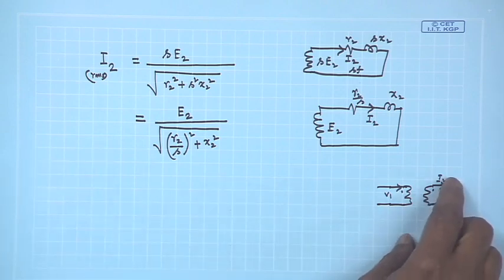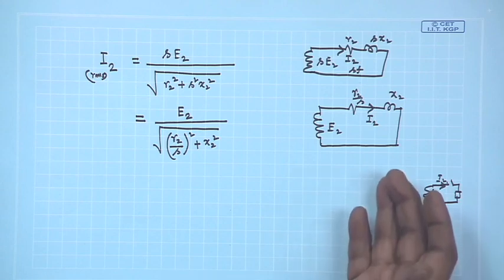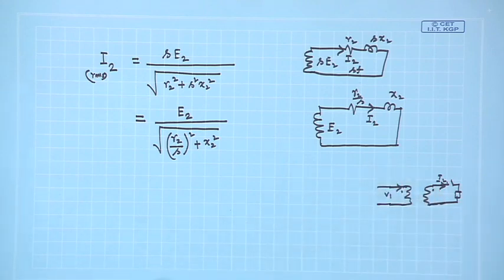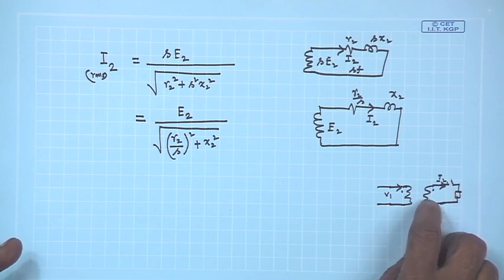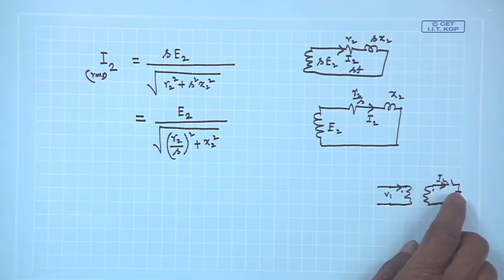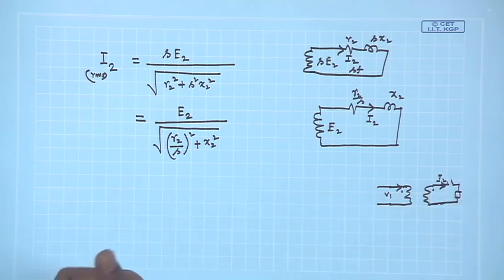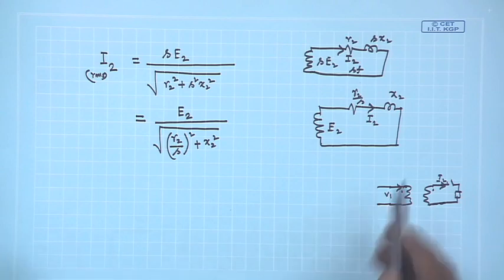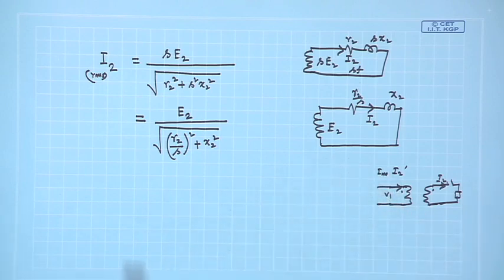So, the moment you close it, but how can it manage to do that? Under no load condition, it was drawing only the magnetizing current to establish the flux. The moment you close the switch, I am sure there will be a secondary current. Therefore, the extra MMF which is now brought into this system, because you have connected a load on the secondary side, primary cannot but draw additional current called reflected current, apart from the magnetizing current, whatever it was drawing.